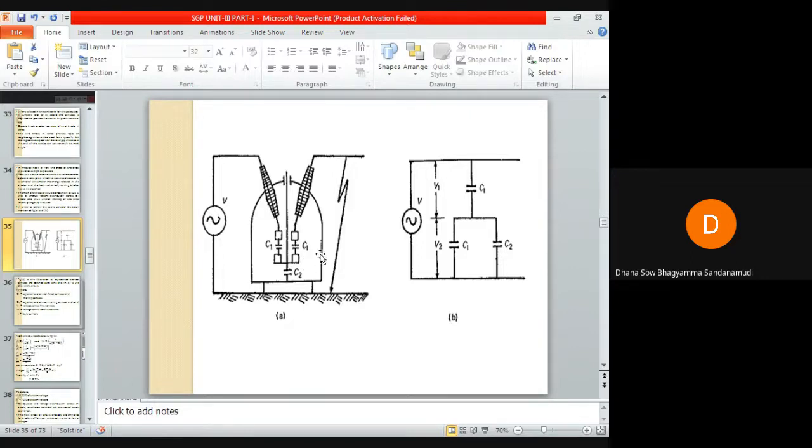You know the property of a non-linear resistor. We have discussed the non-linear resistor many times in the previous classes. So to equalize the voltage distribution across the breaks, nonlinear resistors are connected across each break. Plain break oil circuit breakers are employed for breaking low currents at comparatively low voltages.